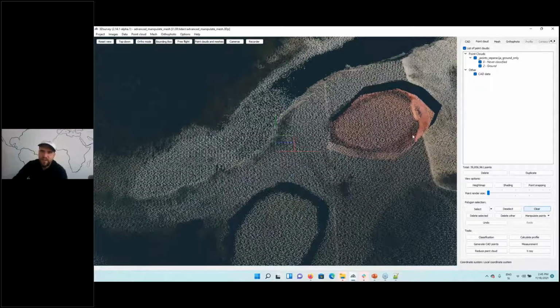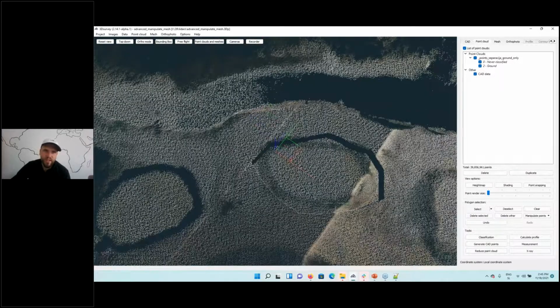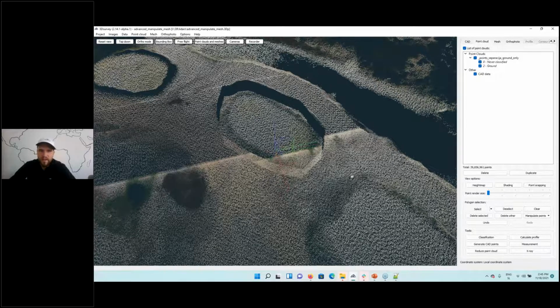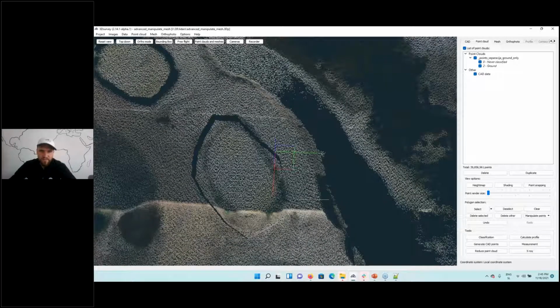And if you do that, then write into the report based on the information from the client, here we lowered points by 2 meters because an additional 2 meters were excavated. That way we can also take that information into account. So, okay, these were some examples on how we can manipulate points and surfaces using the manipulate points tool and how we can use the triangulate function.